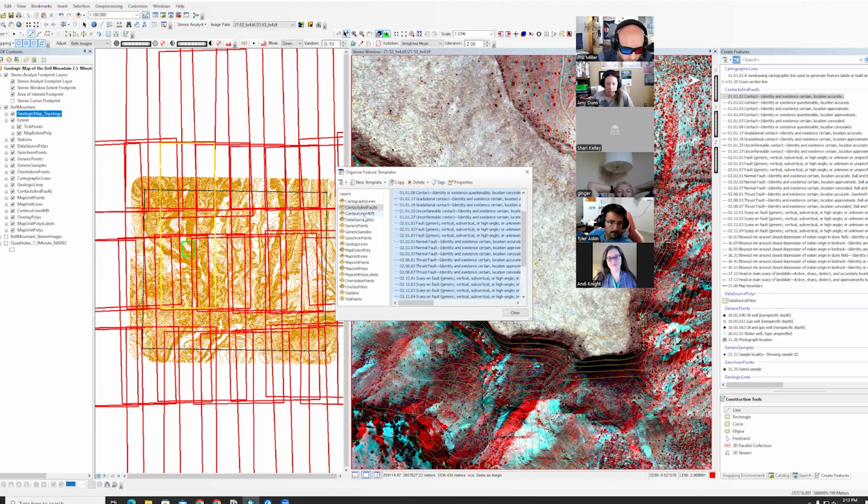You can ignore the contour lines and tick points and map extent poly. You don't need to set the location source or data source for those. That is already defined for us in our projects when we are creating the mapping kits for you all. So same process as we did last time. Go through, set all the data sources, set all the location sources for this information.